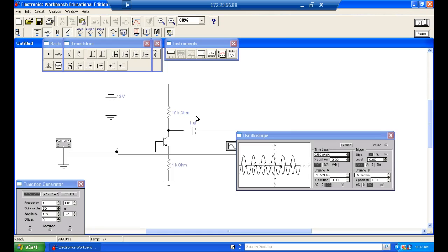So 25% efficient means that to get 100 watts out, I would have to put like 175 watts in from my power supply to get 100 watts out. So the problem with Class A is they're very inefficient, as far as what power you get out compared to what power you get from your power supply, not your signal. Your amplifier does not create power.